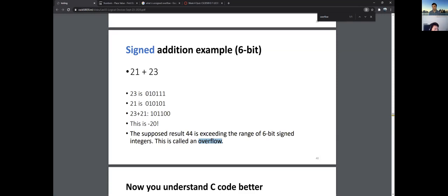And you can corrupt it two ways, right? You can corrupt it by adding two large numbers, or rather, large enough numbers. After you add, the result doesn't fit into, say, 5-bit or 6-bit precision, and then it looks negative, which it shouldn't. It just doesn't have enough bits to store the positive value. And the same thing can happen for negative numbers. You might get too small a negative number that doesn't fit, so it looks positive. So that's what happens.